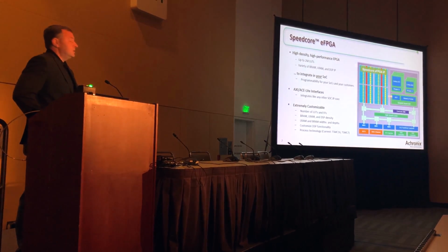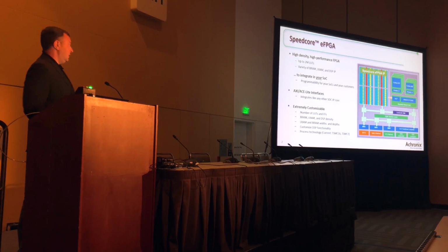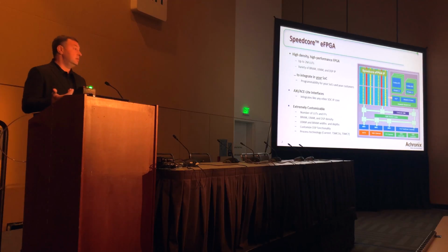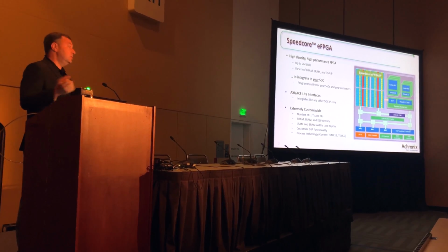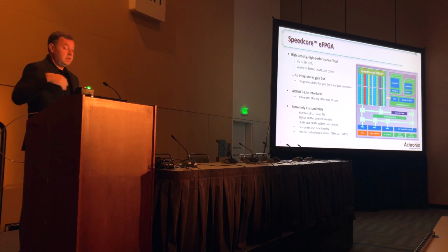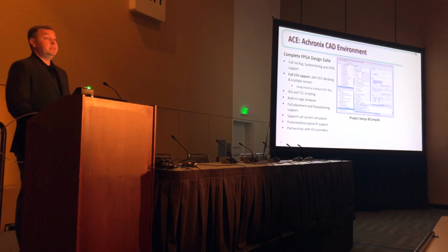Typically, we have AXI and A-Slide interfaces. It's an FPGA, so the interfaces can be anything you want. AXI and A-Slide tend to be common. And because it's an embedded FPGA and we can do something different for every single device, it's extremely customizable. So you, the SoC designer, get to decide how many lookup tables and how many flops, what the density of VRAM, LRAM, and DSP blocks is, what the aspect ratio of the LRAM and VRAM blocks is, and whether there are any special features that you want in the DSP. And of course it's your ASIC, so you decide the technology node and the metal stack.